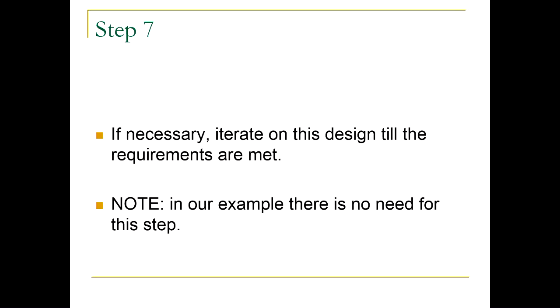What could have happened? You could have chosen crossover frequencies of the compensator too close to the uncompensated or desired crossover, and then this amount of lag could have affected more what's happening around this frequency. So if that happened, you may not have obtained what you wanted to obtain. And if that happens, you need to repeat.